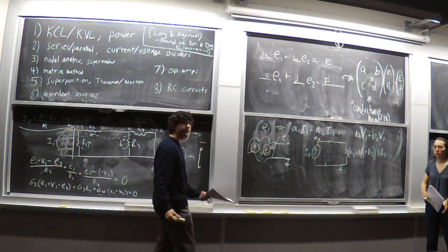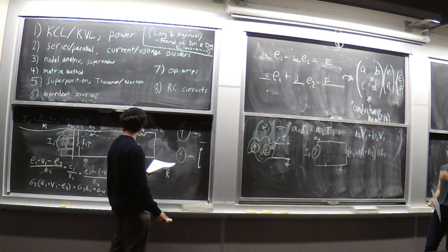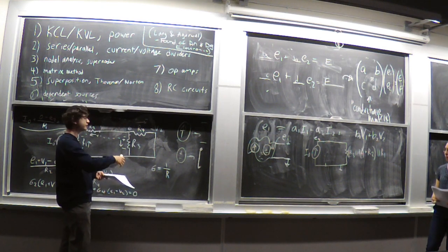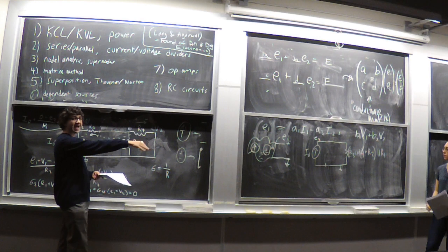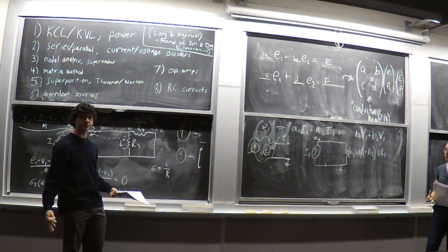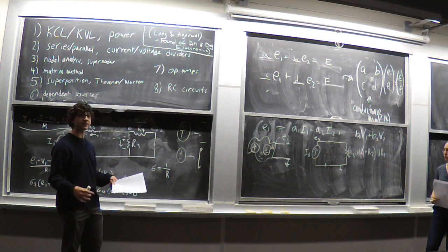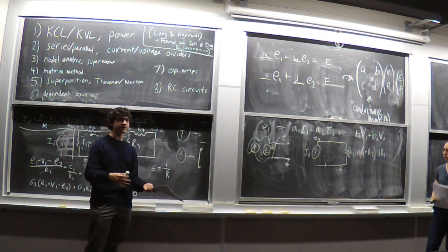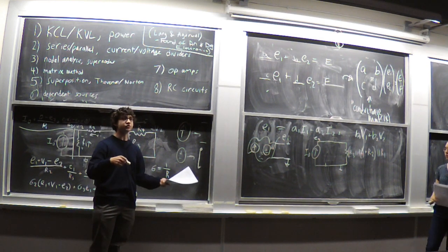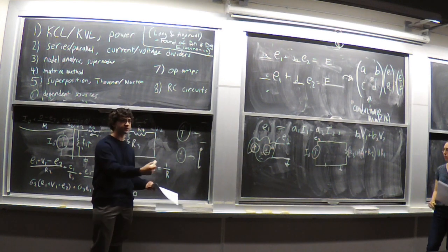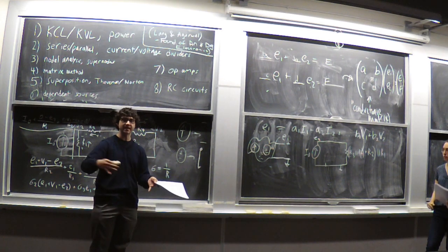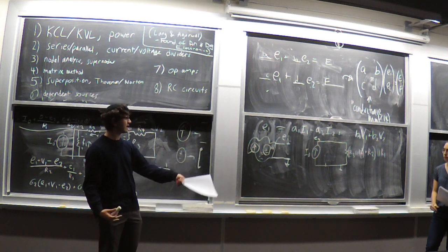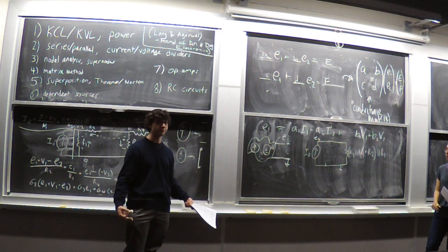One thing to note, though, that is important to keep track of, if you were trying to solve for E1 or something like that, E1 kind of got swallowed in that combination of all of the resistors. And so it is important to keep track of, you can't just get rid of everything and then assume that the node you're left with is the node you were originally looking for. You do need to keep track of where all of the different nodes got collapsed in as you were combining resistors. But clearly superposition makes the analysis a lot easier to do.